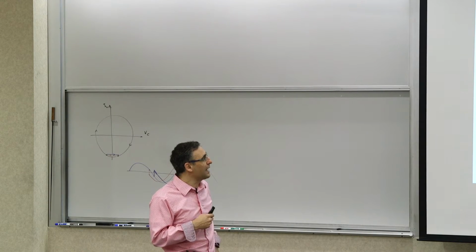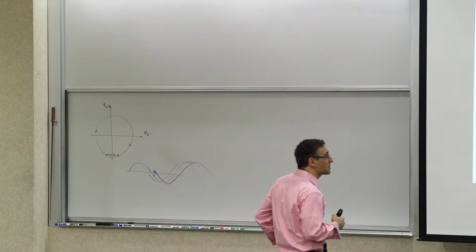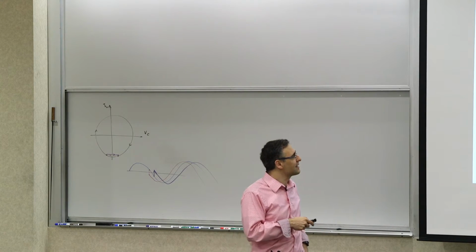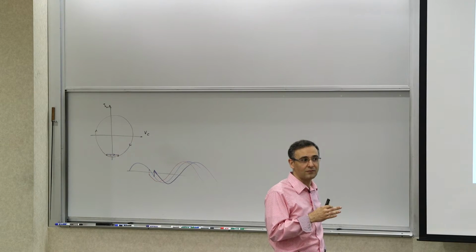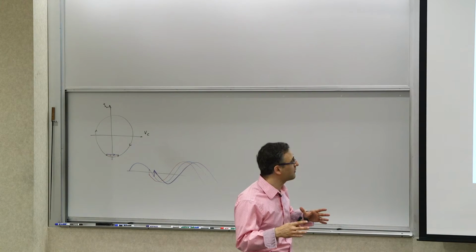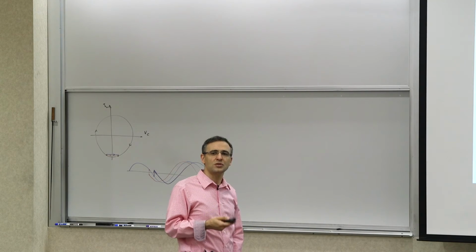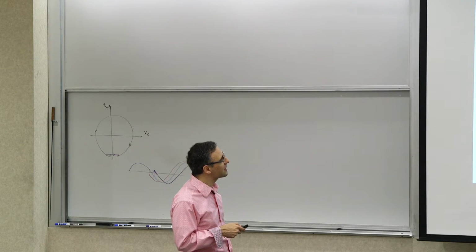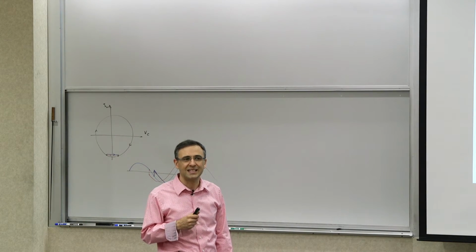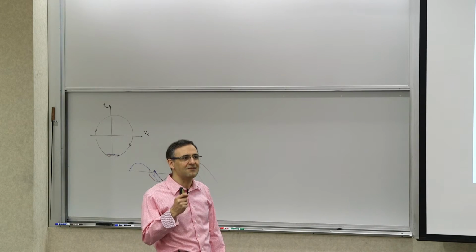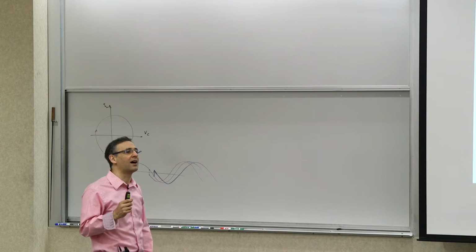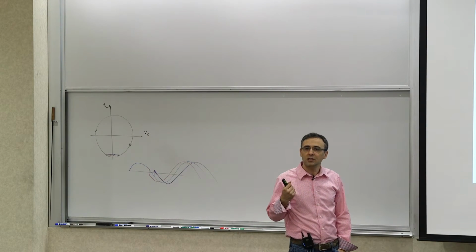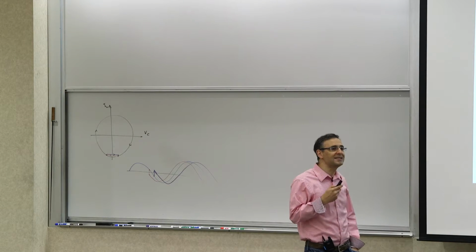Now, in devices like MOSFETs, for example, the 1 over f noise can be pretty large and prominent. If that is the case, this noise can be pretty dominant and it can cover a lot of stuff, and it can basically just dominate your phase noise. So you're interested in reducing this effect to the extent that you can. And how would you reduce that? The good thing is that it gives you a knob to turn, C naught, the DC value of the ISF. So if you want to minimize this upconversion of low frequency noise, 1 over f noise for example, you need to minimize C naught, the DC value of the ISF.